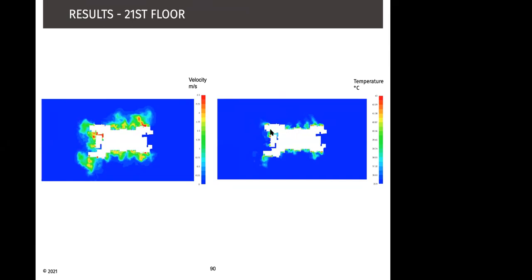We want to study the inlet temperature of each ODU to make sure that the inlet temperature does not go beyond the operating range. For some ODUs, it's 48 degrees. For some ODUs, it's 52 degrees. So we want to keep that within that particular operating range.